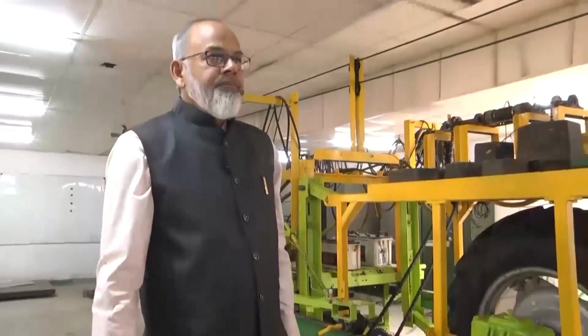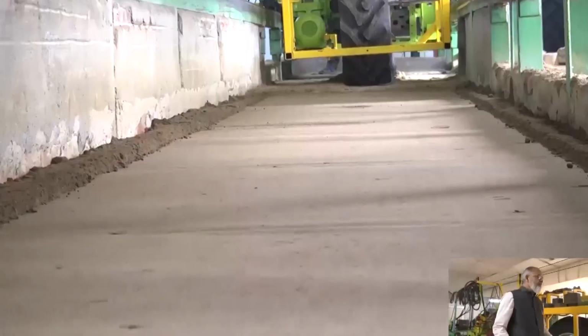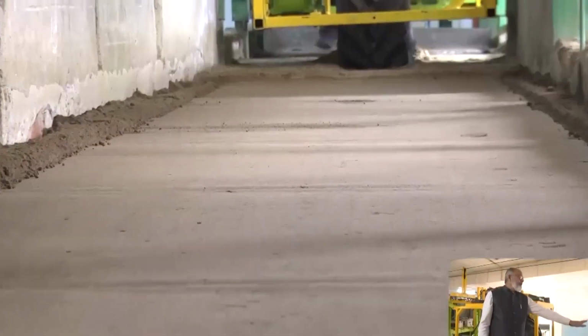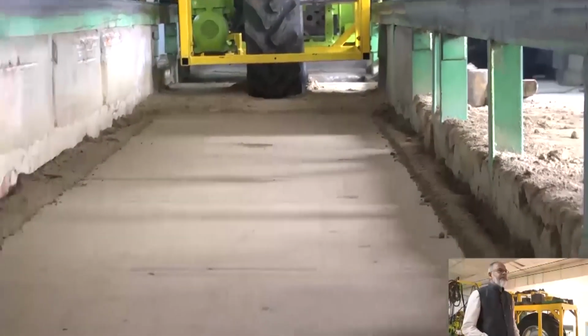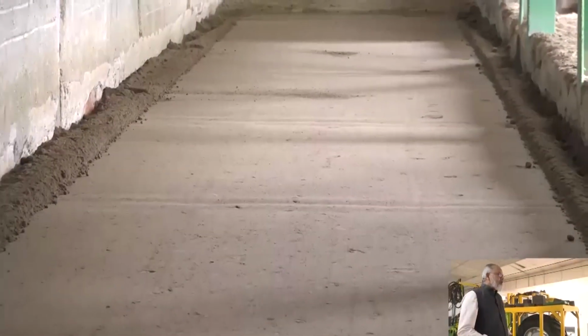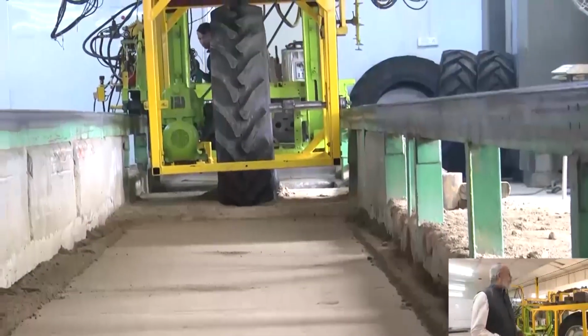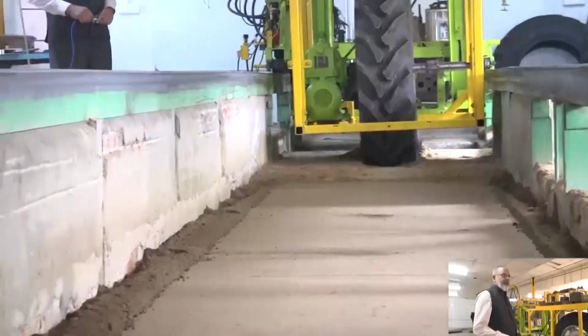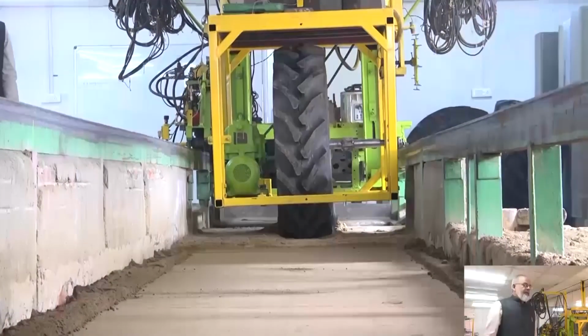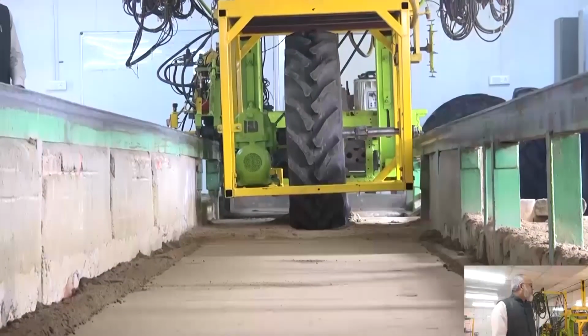Now, I will show you the soil condition before starting the experiment on tractive performance of a tire. You can see the soil bin, it is very well leveled, and we have already measured the cone index. The average cone index value is around 630 kilopascal. So, we will start by switching on the power supply to the motor. Now, we have switched on power to the motor.